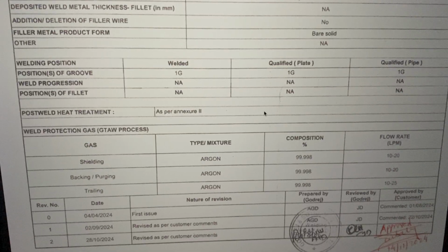So are we going to do some aging, are we going to do some hardening, other heat treatment procedures which are going to either increase the strength or soften the weld and increase the ductility, toughness. So it is essential to consider a post weld heat treatment also for the joints which are critical to our equipment, and specify that in the annexure as to what heat treatment we are going to do.